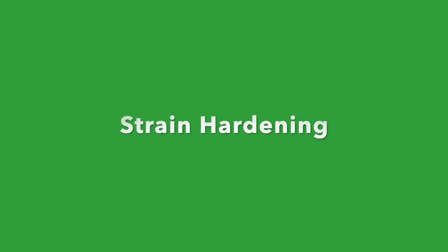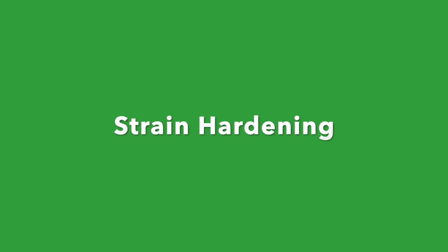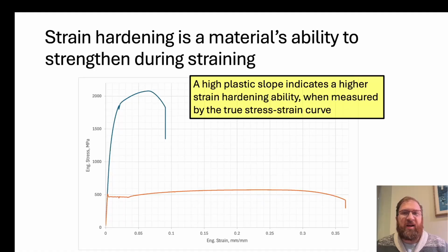In this video, we're going to build off of the last one where we calculated and plotted true stress and true strain for a metal. Here, we're going to build that into determining strain hardening, so determining the strain hardening of a sample.